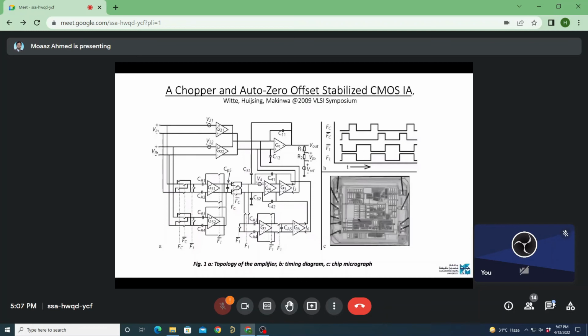What we essentially have is a current feedback instrumentation amplifier, but the problem is that we don't have a chopper, and we have these added offsets, V21 and V22. So their offset is not cancelled, but they will perfectly determine the CFIA gain with the ratio of the resistors R1 and R2. So this is perfectly fine.